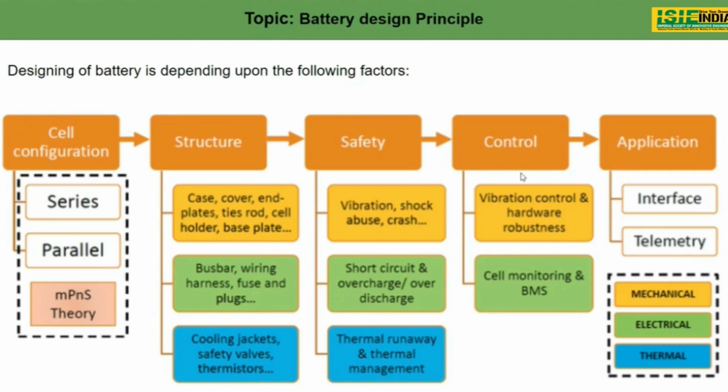The fourth factor is control. While talking about control, it is battery electrical control. We have seen how to select a BMS depending on the number of series and the current rating. When we select a BMS, it has the capacity to cut off a battery pack at a certain level, to avoid overcharging, over voltage, and under voltage. So these controls are very important in a battery pack.